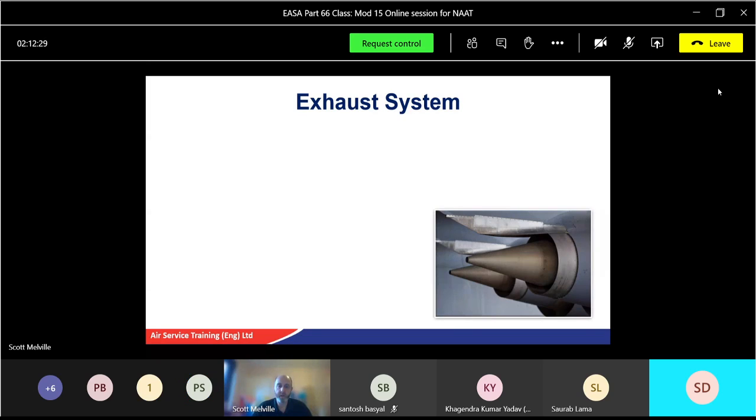For the combustion. So 80% for cooling air, we've got 20% for combustion, and that 20% gets split again into 2 more percentages. What were they? 12 and 8. Yeah, 12 and 8. Which one of the 12 and 8 goes through the swirl chambers? It is 12. Yeah, 12% through the middle. The swirl chambers, which are like vanes, spin the air as it goes through. That helps combustion, yeah. Good.